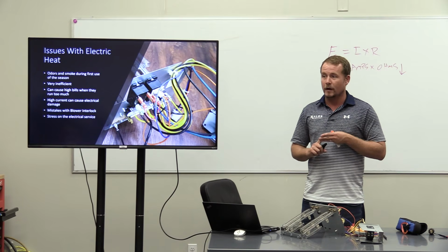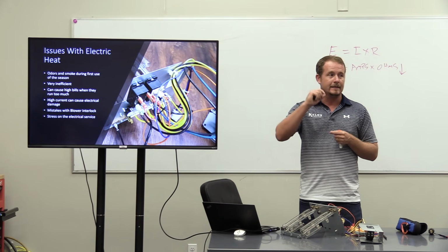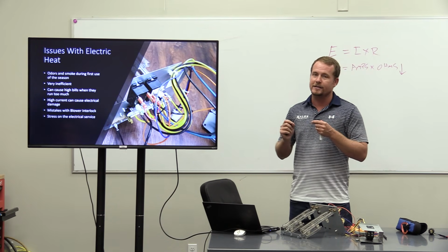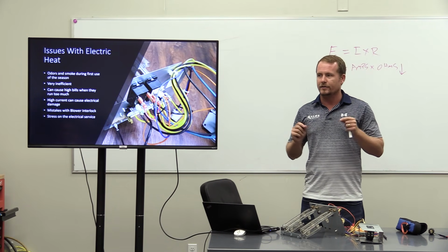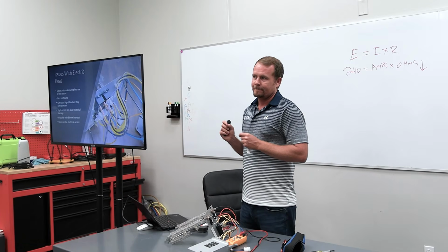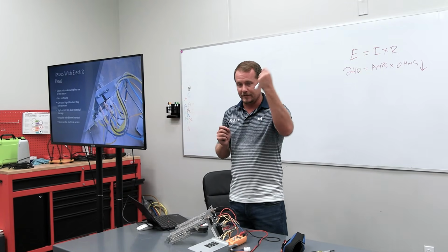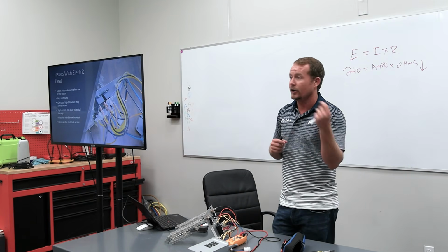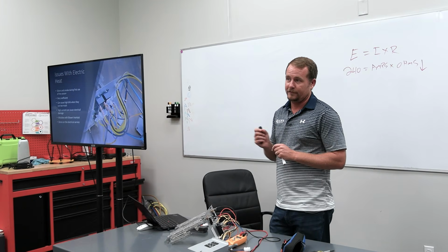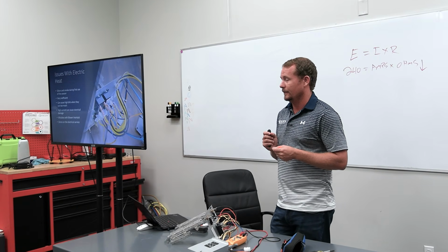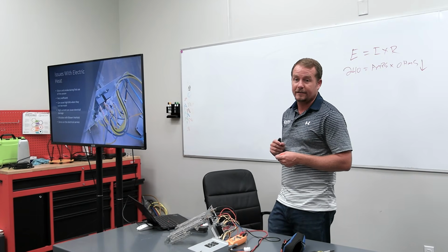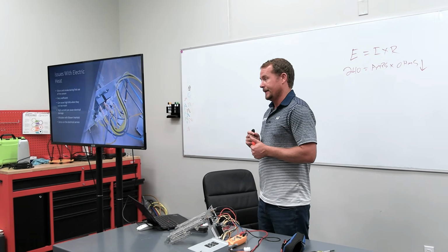Make sense? Wire sizing to a system that has heat strips in it is going to be one of the most important elements. Even if you say, all right, I have a burned up wire inside this unit, I'm just going to grab a number 14 off my truck and wire it back up. In fact, one of the guys I worked with at my previous employer got let go because he rewired heat strips with just a roll of number 14 off his truck, not paying attention to the fact that it obviously isn't going to handle the current it was drawing, and it ended up creating a little fire inside the unit, which was very problematic.